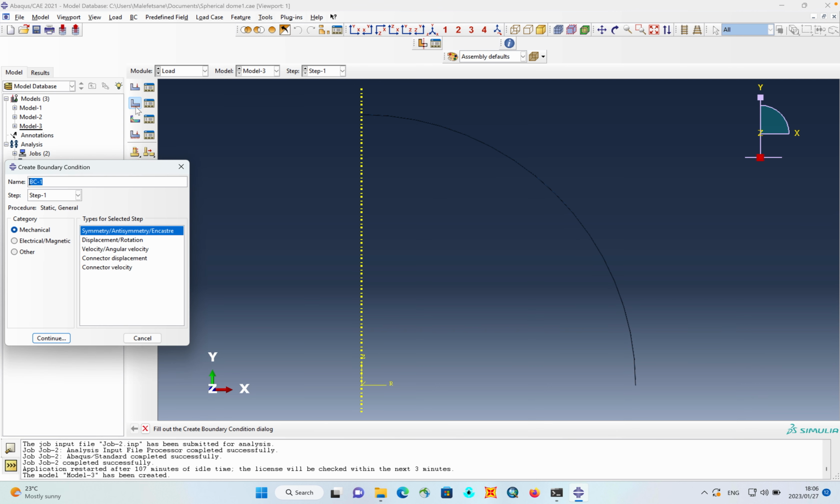All right, from there now we can go to assigning our load. First, let's put in our boundary conditions. Boundary conditions are extremely important in this case as well. In fact, my lecturer did say that if there's one thing you should be careful with in finite element analysis, your results or your solution is heavily affected by two things: your boundary conditions and your mesh. Those two, if you get them wrong, then it's over.